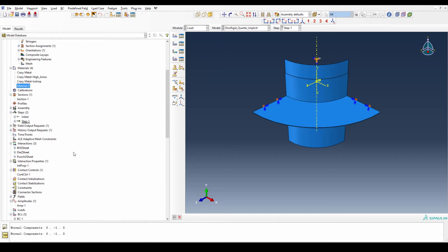But the physical accuracy of the results might be affected very well, or the computational time, if it's a non-high speed operation, right? If you, for example, model a machining process and the chip formation, that might be an interesting case where it's not very dynamic. However, it's a fast process, so the chip has a low mass, but it happens so fast. So then in this case, the explicit solver might actually be the better choice.